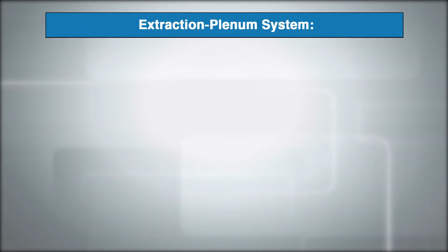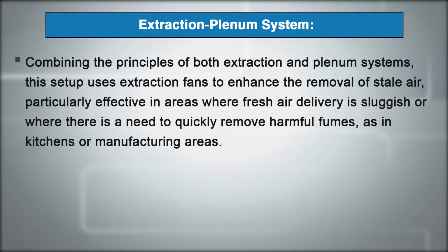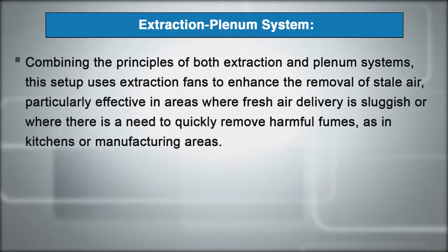Extraction plenum system. Combining the principles of both extraction and plenum systems, this setup uses extraction fans to enhance the removal of stale air, particularly effective in areas where fresh air delivery is sluggish or where there is a need to quickly remove harmful fumes, as in kitchens or manufacturing areas.